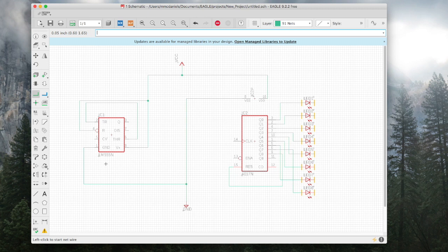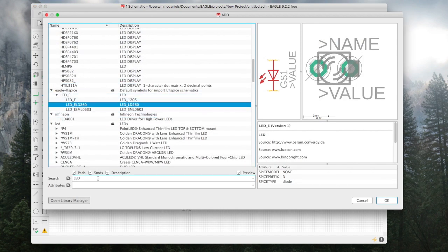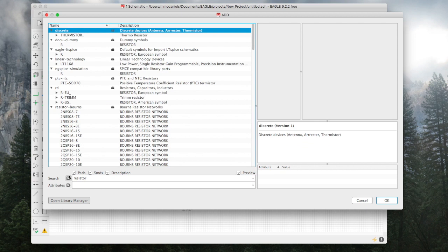So we're going to connect up the 555 as an astable multivibrator or an oscillator. It'll generate a square wave, and the square wave will go to the clock input of the decade counter. Here you'll see I'm connecting to pin 14, the clock input of the decade counter. Now, with a few connections here and there, we'll be able to wire this up as an astable multivibrator. And you'll see I'm searching for a resistor to put resistors in place.